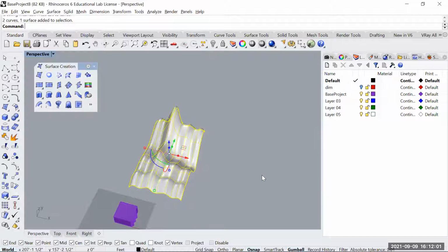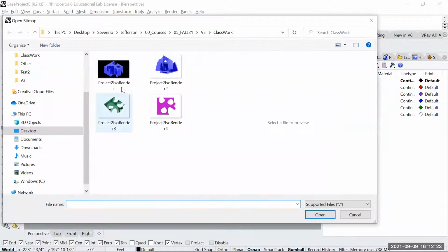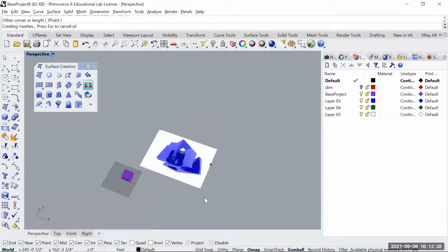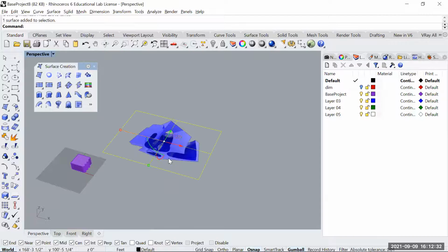Yeah. So we have planes. You can create planes obviously in many ways. So vertical planes, 4-point planes. Some of them are very useful for specific tasks, and when that task comes, that's when you know you need it. No? So you can create a picture plane. We're going to use it in a second for actually one of the projects. So basically you click on picture plane, you select any image, JPEG or whatever, and then you just introduce an image here, no? Into the project that you can trace and so on. We will use that in a second.